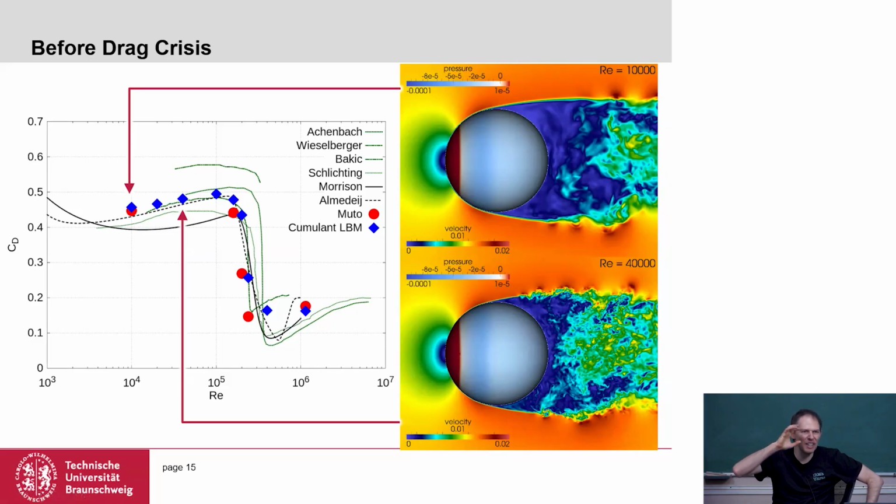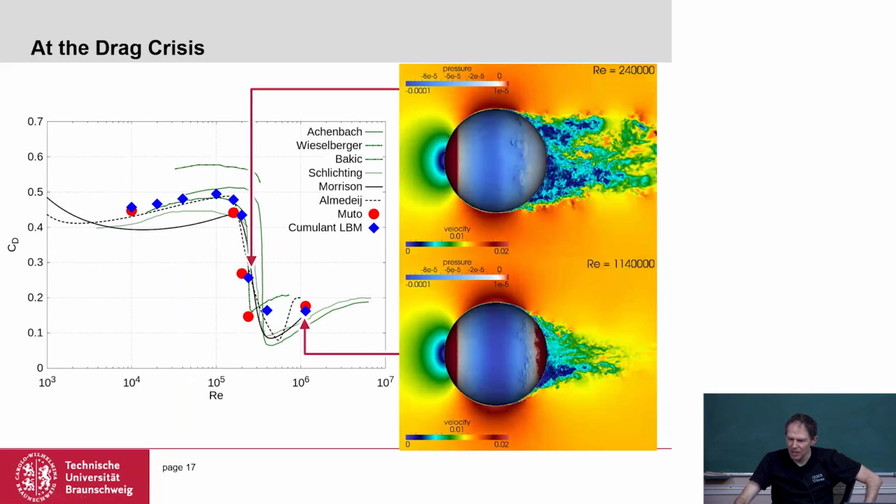then we're using Cartesian grids and we make it coarser outside. Tomorrow we'll talk about grid refinement and how we do it. But we need a resolution of 500 points here. And if we do this, we can actually capture the transition of the boundary layer with these cumulant methods, not using any turbulence model at all.